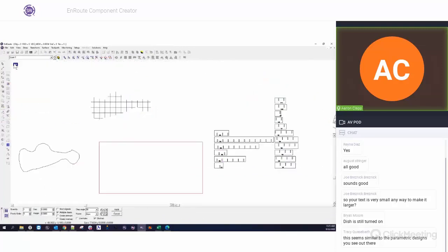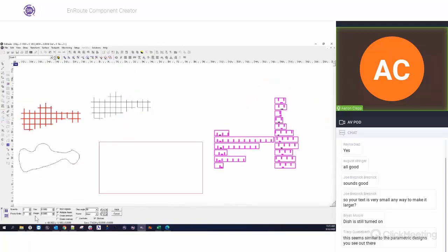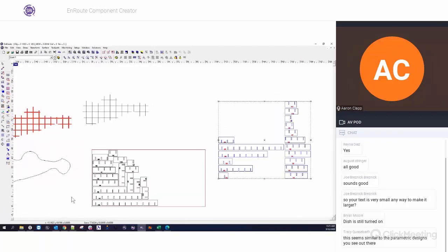And we're going to say quantity of 1, multiple sheets if necessary. Maybe we'll do a gap of 0.5 inches. No, 90 degrees is all we want in this case. And just like that, now we've nested all those pieces. This is ready to cut. We can toolpath it, send it along its way, and it's ready to go.